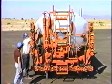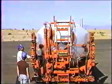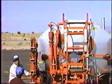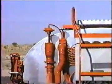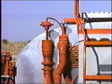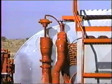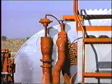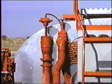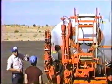This line goes to the bypass valve. That bypass valve is an air-operated pressure regulating valve, also an air-operated relief valve. A very simple valve. Just envision a pipe with a cap over the top of this pipe, and we push down on this cap with the air can. That's the brake can up on top. We use it just as an air cylinder.